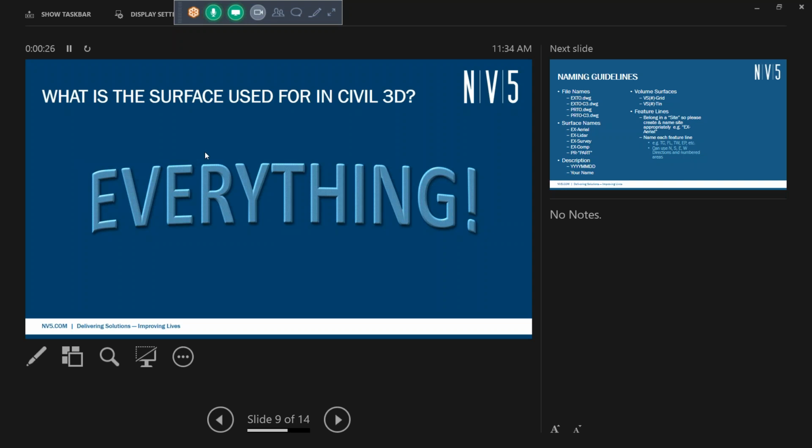So we said existing ground profile above proposed trench alignment. Typically, we don't use that surface to call out set elevations. We're not really designing off of that. The level of accuracy is pretty low because usually that comes from our aerial topography.